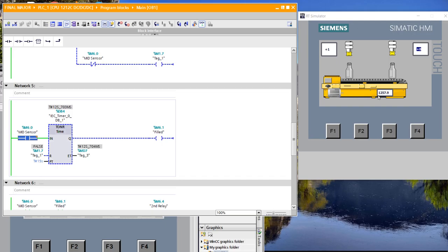So as the mid sensor has got a bottle, the motor is turning off, and the solenoid valve has started filling the bottle. As you can see here, the time is there, 13 seconds, 14, 15. We have allocated a 15-second time for filling the bottle. Okay, now as you can see, the time has been completed, then the motor has been started.